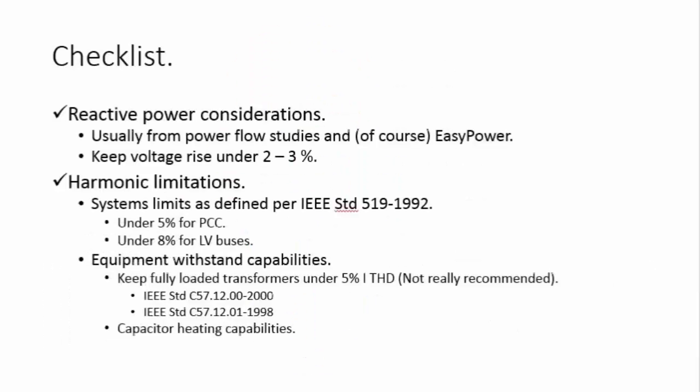Now, let's go into the first. And I will make a sort of checklist to review when we're trying to design a filter. So this is the procedure, more or less, that we were talking about. Now, the first step for a filter is to ask, what do you need the filter for? The most common application of filters in power systems is harmonic filtering, obviously, but it is also power factor correction.